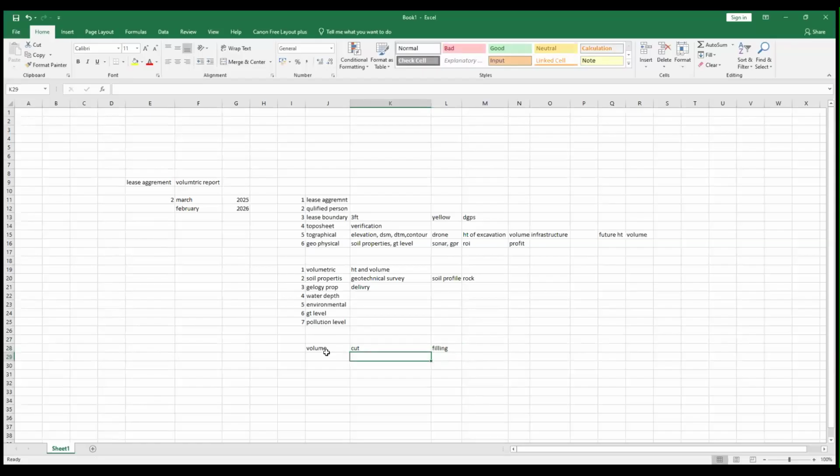And this cut volume is also calculated in order to check the least quantity which the person is entitled to excavate. They have two different locations in every quarry: you will have your excavation site and you will have your dumping site. These two sites are mandatory in all quarry areas in order to calculate cutting and filling volume.